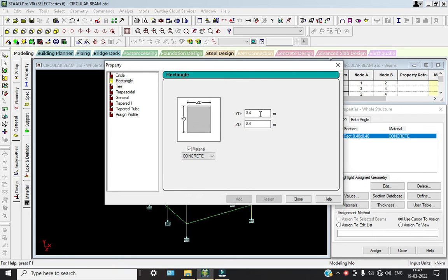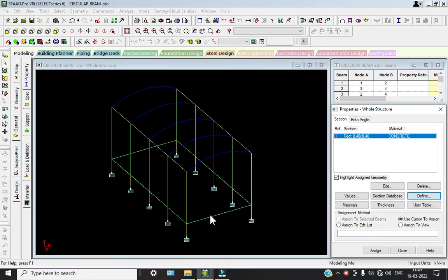So after that we're going to take the z-axis beams. So we can select, right? But here we don't have any beams. So we need to add beams for that. Click on add beam, select these points over here and over here, right? So we are done with it.